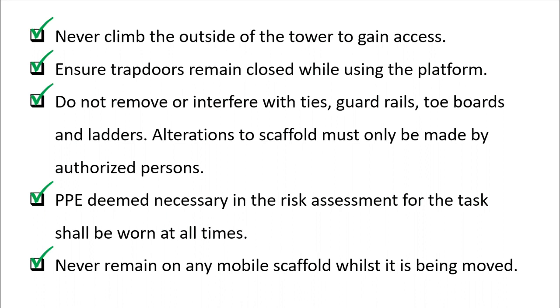So before you move or transfer the mobile scaffold from one place to another place, all persons should go down on the floor before transferring of that mobile scaffold, because when you are moving it may collapse because of unbalanced movement of the personnel on the top, and the center of gravity of the scaffold may be compromised, and then it will tip over and it will be a disaster if someone gets injured or dies.